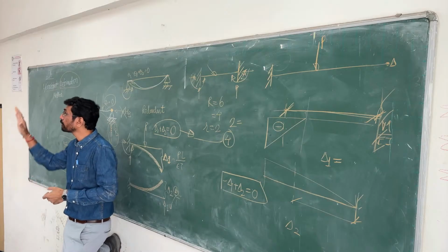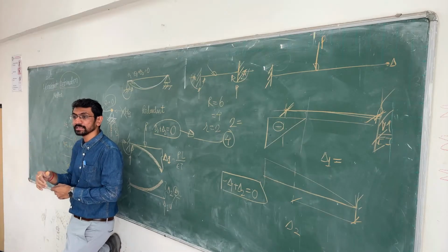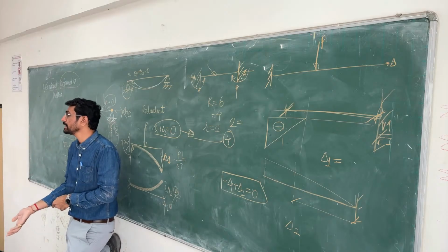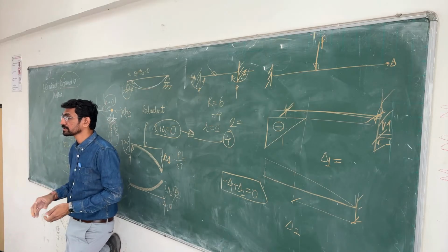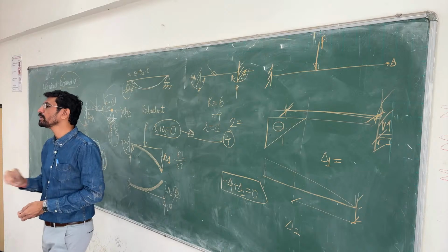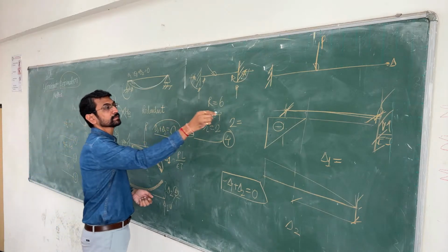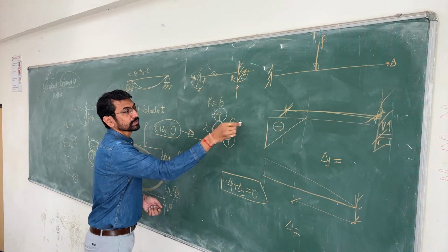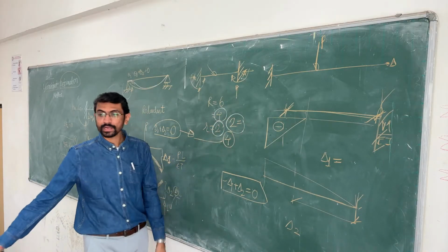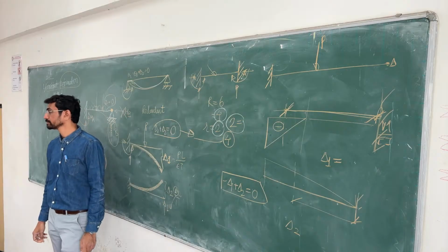But in our normal frame structures, residential buildings, commercial buildings, multi-story structures, in beams you hardly have horizontal forces. Right? So capital R becomes 4, small r becomes 2. So you have to find out only 2 additional redundants.